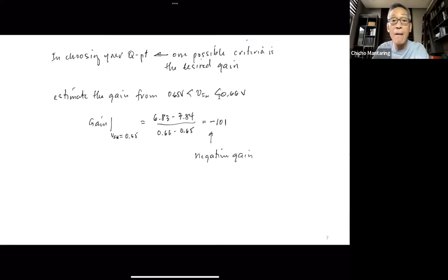180 degrees out of phase. By the way, this is not like an op amp where you can amplify DC. Here, your input signal has to be a time varying signal, and your gain is applied to that time varying signal. That's why we say 180 degrees out of phase or inverting. Any questions with regard to the common emitter amplifier?